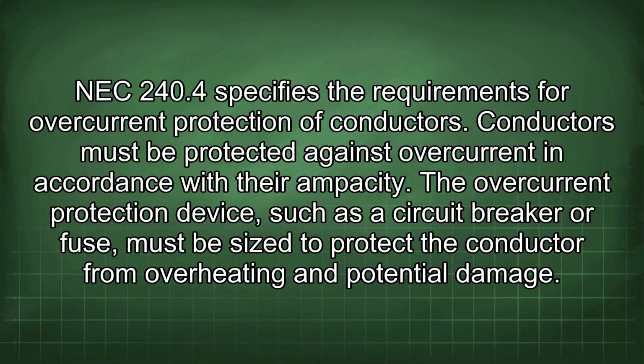NEC 240.4 specifies the requirements for overcurrent protection of conductors. Conductors must be protected against overcurrent in accordance with their ampacity. The overcurrent protection device, such as a circuit breaker or fuse, must be sized to protect the conductor from overheating and potential damage.